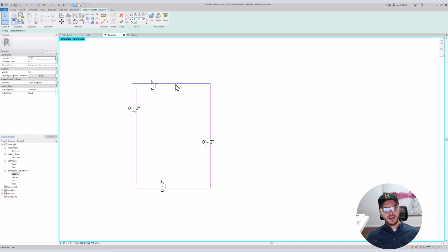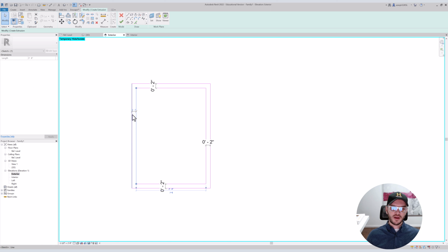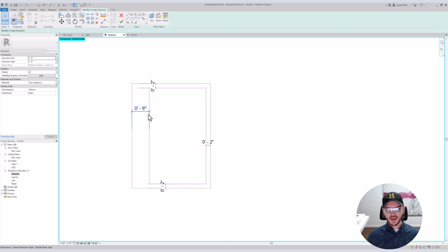If you noticed, I started all my dimensions from the outer perimeter of this window frame. I did that because if we're going to change this dimension by using a parameter, by starting the dimension from this side, if this grows, this will grow this way, and not the other way around. So that's why we do that.